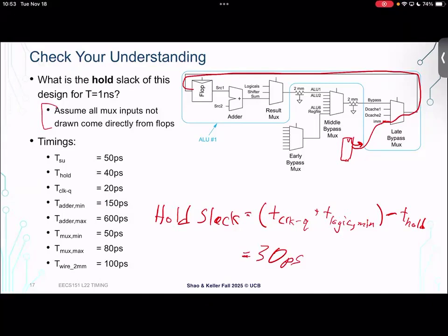In the research or academic designs that I have taped out, where we don't care that much about performance and want to be very conservative and have higher odds that it works, I usually target a slack of like 100 picoseconds, something on that order, just to make sure there's lots and lots of extra margin.